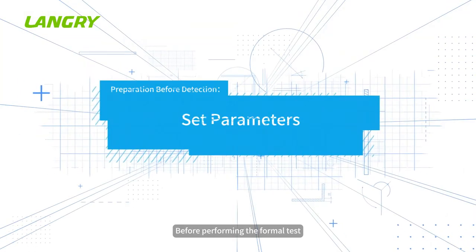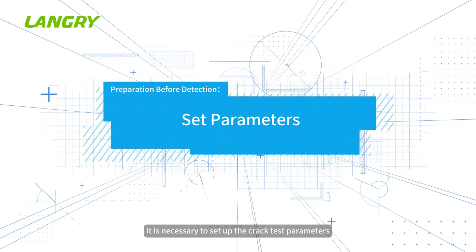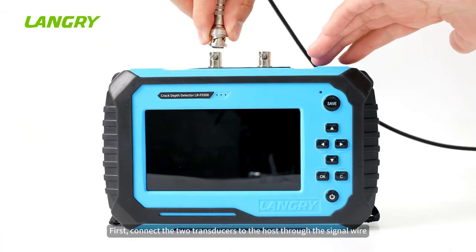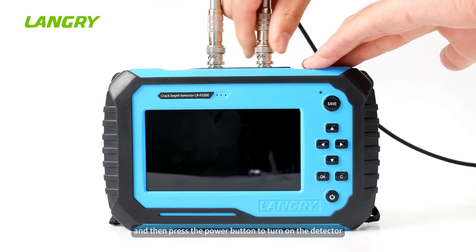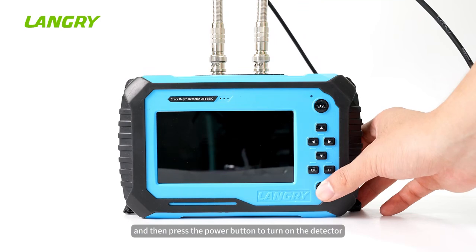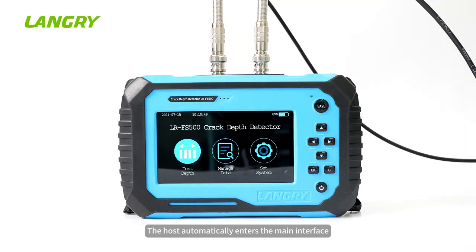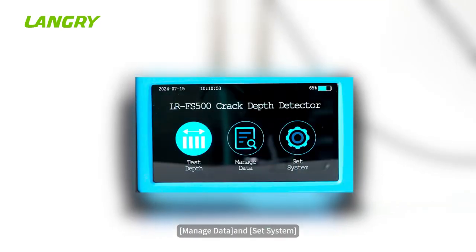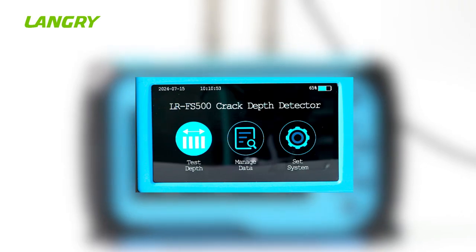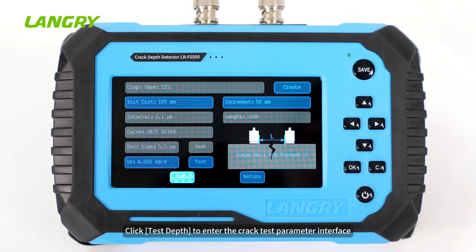Before performing the formal test, it is necessary to set up the crack test parameters. First, connect the two transducers to the host through the signal wire, and then press the power button to turn on the detector. The host automatically enters the main interface. The main interface contains three functions, namely test depth, manage data and set system. Click test depth to enter the crack test parameter interface.